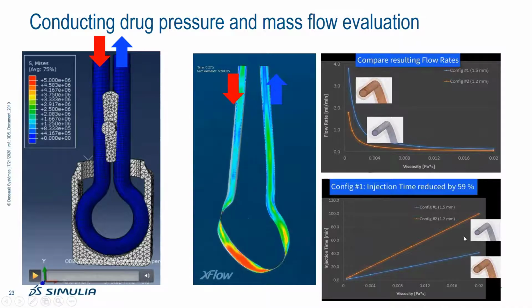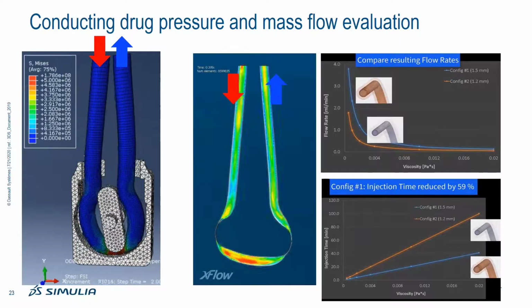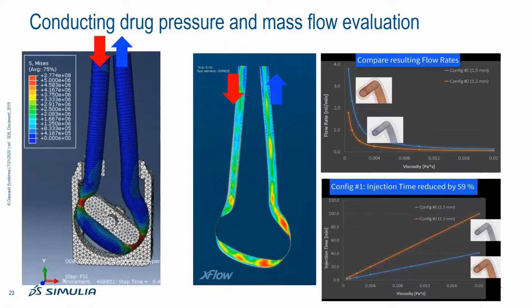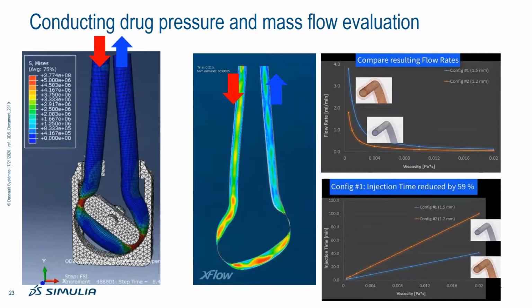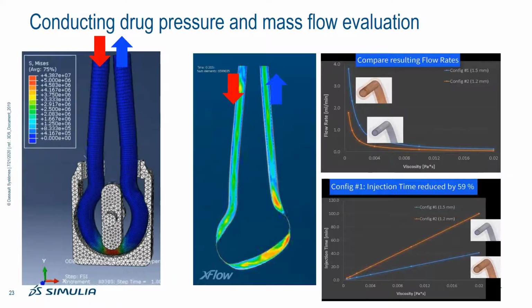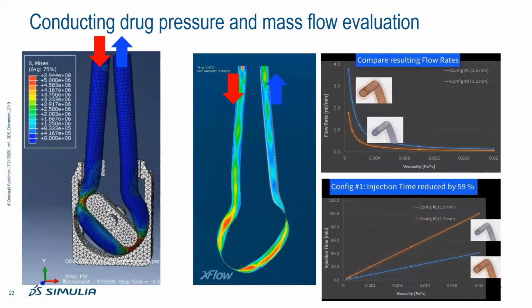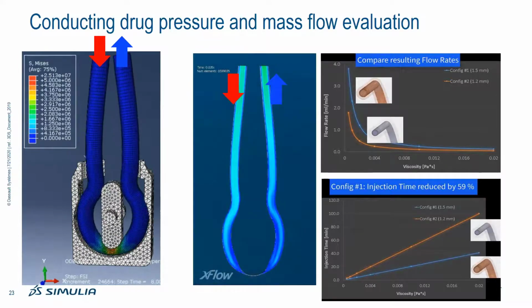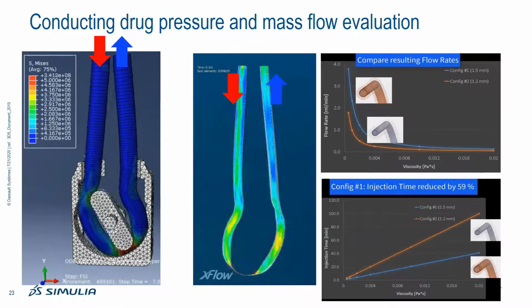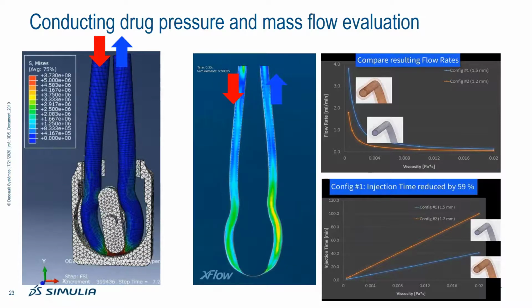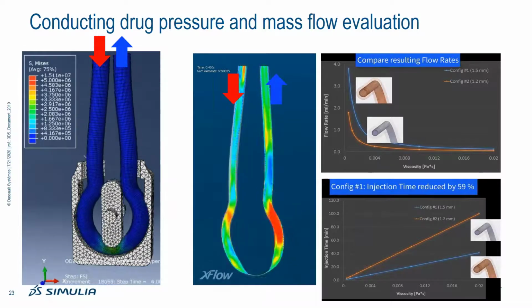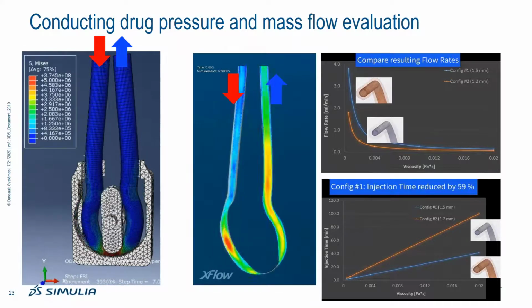Inspecting the results for the fluid domain, seen here, we can inspect the pressure and flow characteristics within the tube, tuning the pump for degree of pinching and resultant backflow, peak pressure capability, flow and flow rate. The engineering team have explored the use of different gauges of tube and other pump parameters so that the best of a great many design alternatives can be identified without ever having to build a physical prototype.